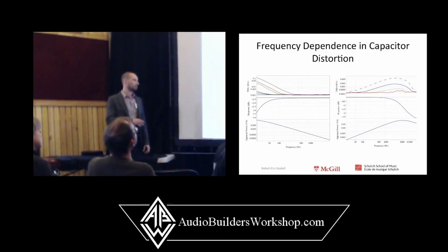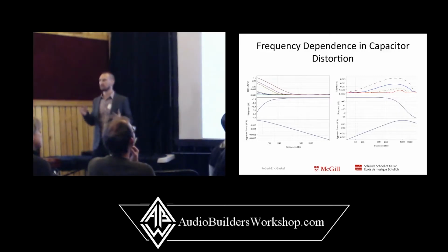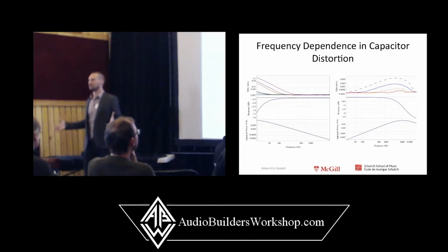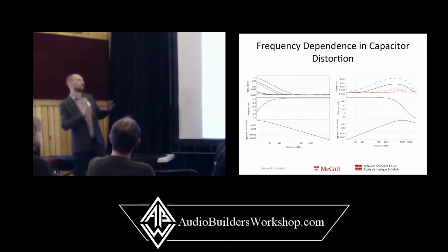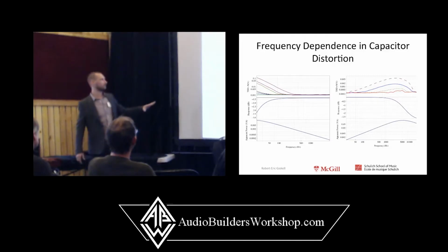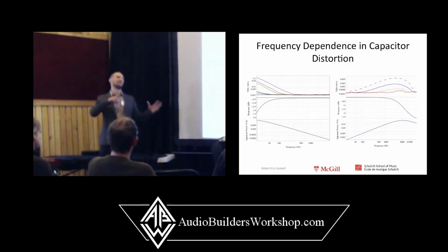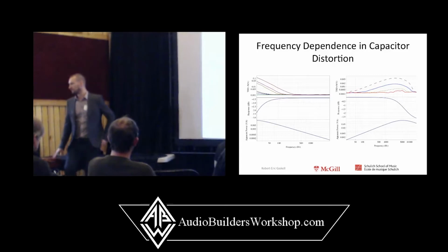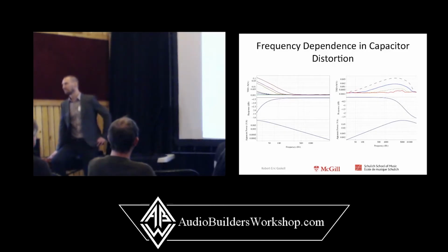People were able to hear the difference between capacitors when I used electrolytics versus tantalums versus PETs up at higher frequencies, though, which was interesting. But typically, unless it's an EQ circuit, and I can't think of a single professional EQ that doesn't use PET or polypropylene capacitors, so it's kind of moot, we see these capacitors used at low frequencies. Remember the original Neve circuit I showed at the beginning: it used tantalums to block the DC and allowed a biasing of the circuit.